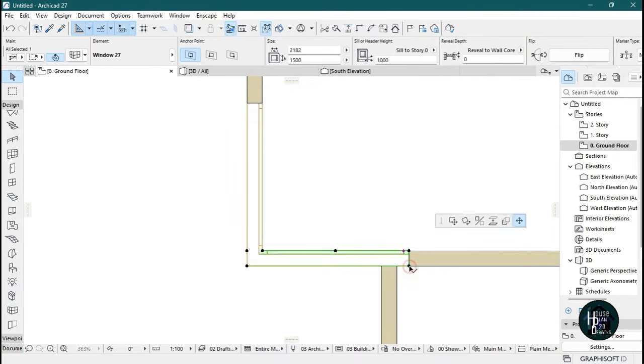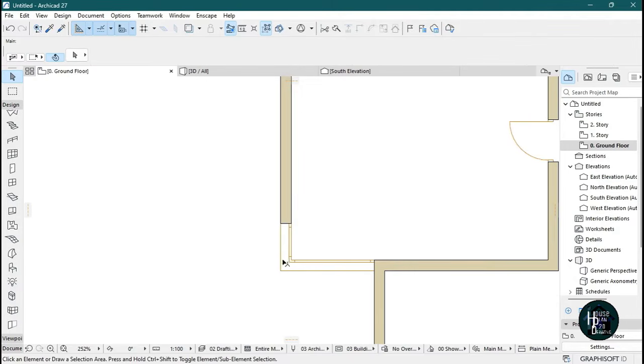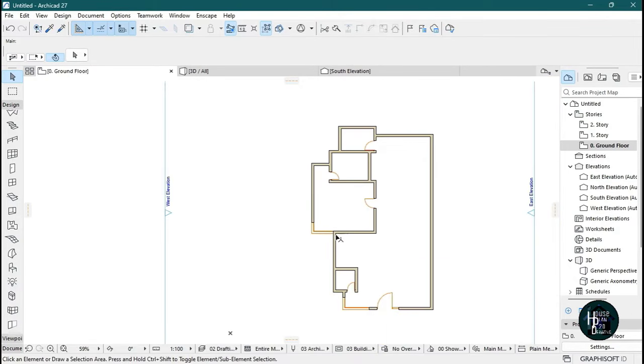Just click on this node. This box is going to come up, so select this move node and move it to this side here. Once you've done that, click this other side, click on this node and move it to just around the side, something small, let me say 1000. Click enter, and you should have something like this, just for this edge.